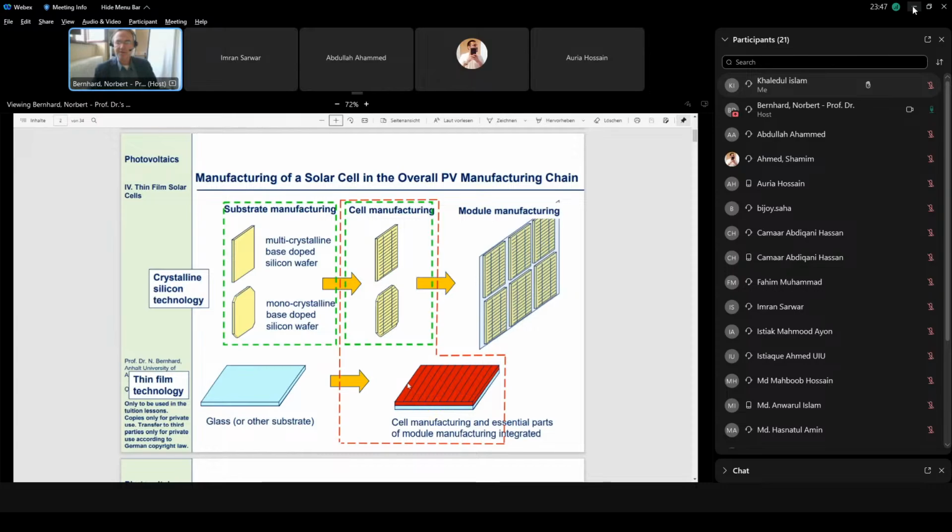For doping, as already said, we just add phosphine or diborane, and we could also alloy it either with germanium or with carbon. This would adjust the band gaps. Alloying with germanium would make the band gap smaller, and alloying with carbon would make the band gap wider.